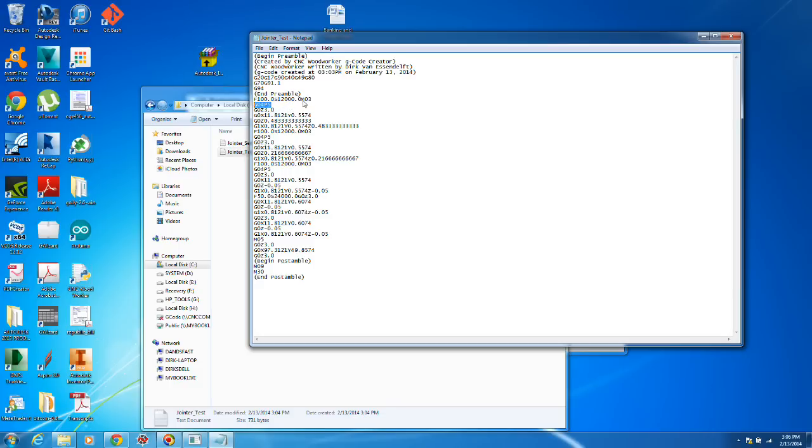That way it gives me enough time to register in my mind that the spindle is actually going and doing what it should be doing before it starts moving anything, and I can kill the process before it starts there. It doesn't happen very often, but when it does happen, it can break a bit if you run your machine too hard. Really easy. So anyway, it goes to safe Z, and here we go.